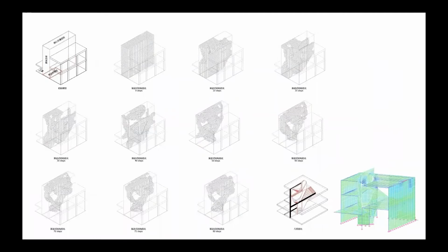The whole design process is actually based on the circulation. Firstly we thought of it as all solid concrete. Then we optimized it with finite element optimization tools. At that time, we used Millipede to delete the unused material, generation by generation, through about 80 iteration steps. Then we polished the surface with ruled surfaces, and translated this optimization into a spatial space.